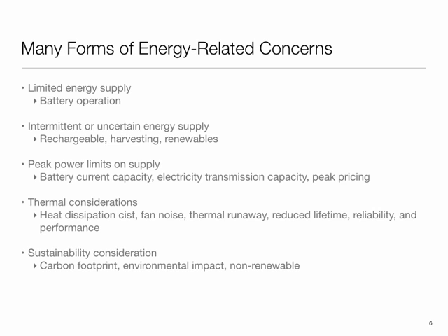Thermal runaway. This refers to the fact that most electronics dissipate heat. If you don't remove that heat, the temperature will go up. As the temperature goes up, to do the same thing, more heat is produced. So essentially, the energy dissipated in doing an operation increases with temperature.